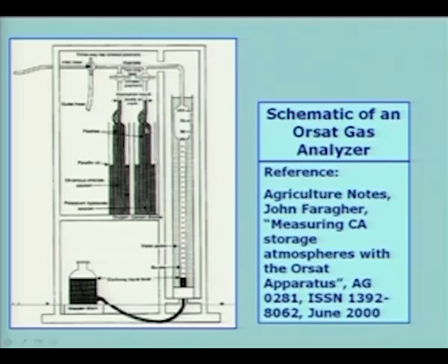So, whatever percentage of carbon dioxide is there in the sample will be absorbed, and therefore, what comes out is only the rest of the gas. So, what will happen is that when you bring it down, this level will go to a higher level, and of course, this will also be at a higher level, because the volume of the gas will be lower by the amount of carbon dioxide which was present in the sample, which has been absorbed by the reagent in this vessel.